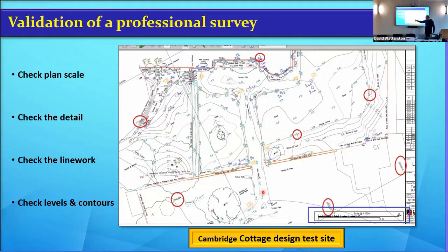And as I say, you can stand on there, you can look through the corner of that building, and then produce that onto the wall or to something else. And if you've got somebody with you, get them to hold a pole or whatever. And then from that point, you can measure bits of detail. And when you get the drawing, put a straight edge through there, and you can find it all links up. So, if it's all good. You know, is the hedge about in the right place, at the right height, at the right width? And stand at the end of there, does that wall look right? You know, because it's probably intended to be built right, and you just want to shoot at the buttresses in the right places. There's lots of things you can quickly go over, which will give you a feel.